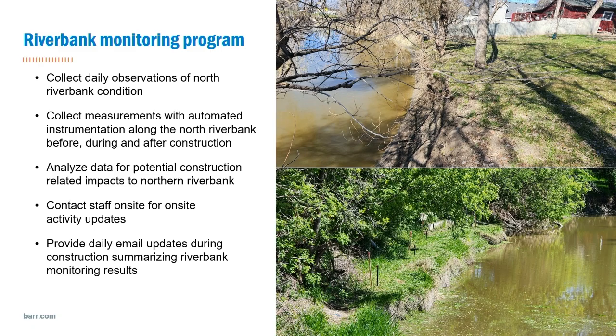As part of that riverbank monitoring system, it's really important, again, to collect a lot of baseline data to make sure that, as the river level goes up and down, we can tell whether that is affecting the riverbank more than the construction vibrations. It also gives us something to compare to if we were to see any thresholds exceeded. During construction, we were collecting measurements with the automated total station along that riverbank, both before, during, and after construction.